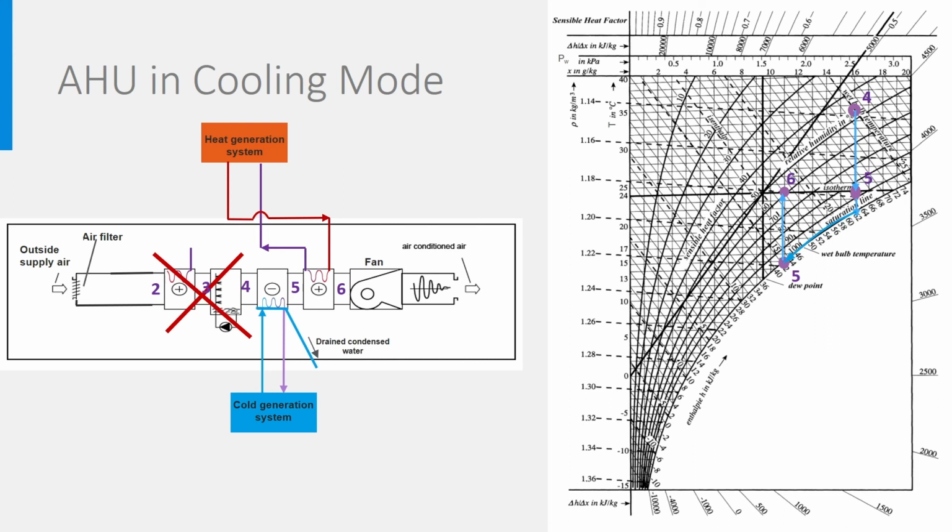To summarize, when cooling above the saturation line, the second heater is not needed. When cooling goes along the saturation line, air is dehumidified and in general cooled too deep, by which the second heater is needed, which is also the reason why there are 2 heaters in air handling units.